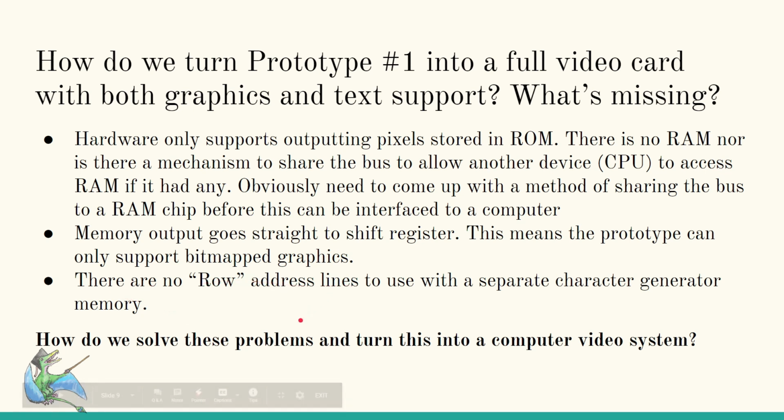On a real CRTC chip, or if you were doing discrete hardware, there would be some additional address lines to tell a character ROM what row you're on. I'm almost out, and I'm going to need some more control lines. We don't have enough discrete control lines to use additional lines on the CPU for the control lines. So it's not a huge problem. Next slide we'll talk about how we could deal with it, but it's a thing.